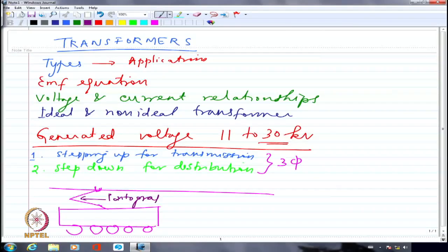This is the pantograph. So pantograph basically is a kind of a brush kind of arrangement which is actually made up of a thick conducting material which is insulated by whatever is the insulator. They may have some plastic, bakelite and so on, and then that is having a U-shaped conductor which is sliding over the overhead transmission line to collect electricity.